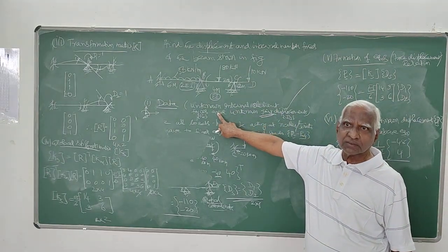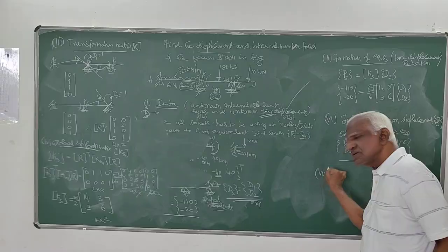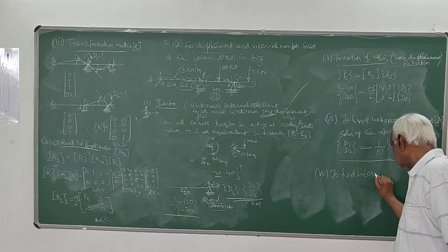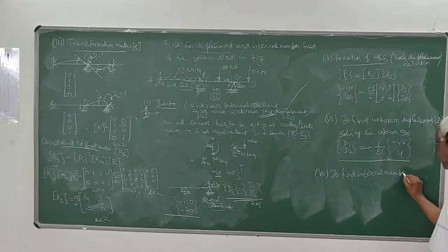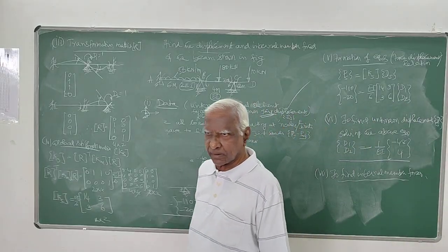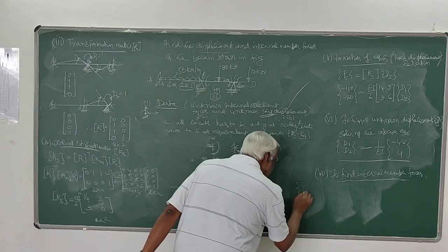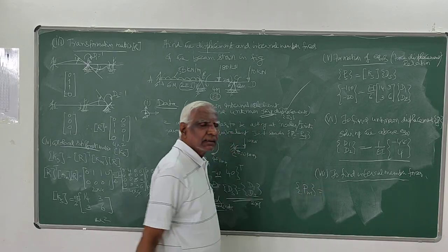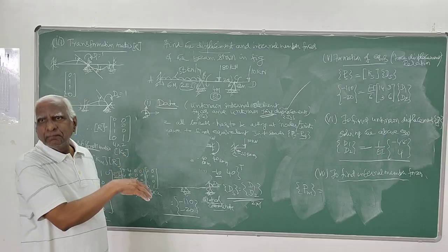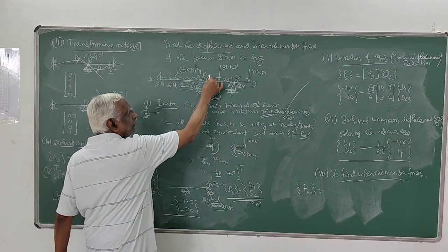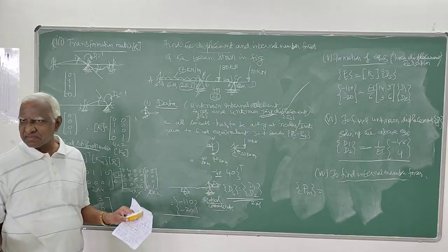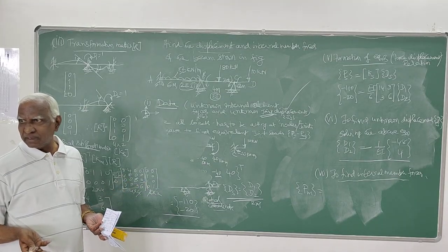Then the internal member forces we have to get. That is our last step, to find the internal member forces. These are the 7 steps I have indicated. Even for the truss problem also I did the same thing. Last step, I will give you the formula that Pm is the internal member forces corresponding to local coordinates. All my Pm1, Pm2, Pm3, Pm4. Once I determine the moments, shears also can be determined by statics. Everything is known, that's all. Clear? That's how we do it.